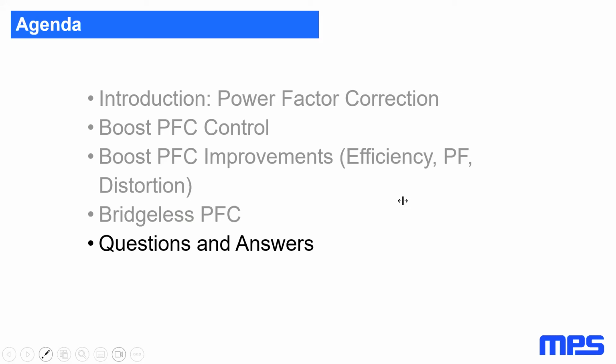Okay, thanks a lot. The next two questions were referring to the bridgeless PFC slides. The first one is, could this type of PFC work bidirectionally? So the totem pole PFC, yes, practically yes, it can be controlled bidirectionally because there are only switches, and so you can always switch them in opposite directions.